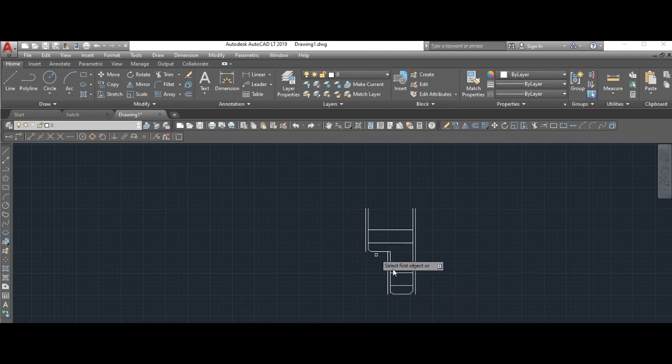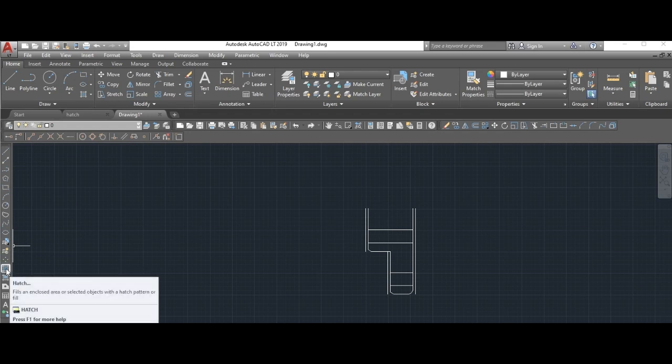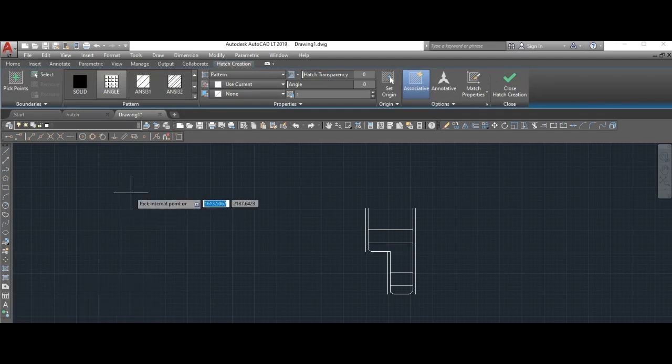Okay, so we are done with that. Press enter. So now the next thing we're going to do is some hatching, which puts some patterns or some coloration or some designs into your diagram. So I come to this tool here. Look at it here, you see it's called a hatch. I click the hatch tool. You can see the different types of hatches or patterns that you require. Let's look for something that is interesting.